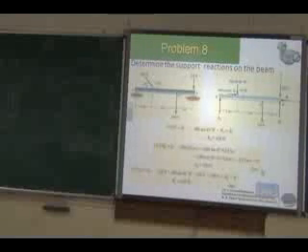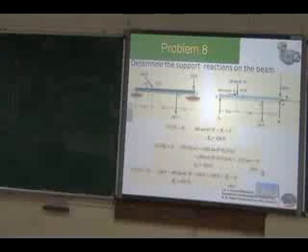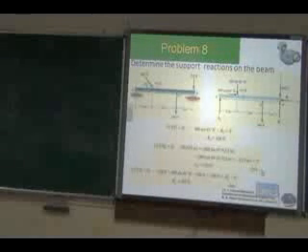But point B is bolted to the surface. At both ends, the bolt's dot is visible. At point A, they have just fitted it. It is not bolted, so you can even slide in x direction. Cannot move in y direction. And the flange below, the surface is just touching. It is not bolted.